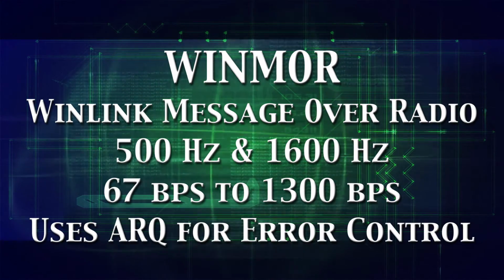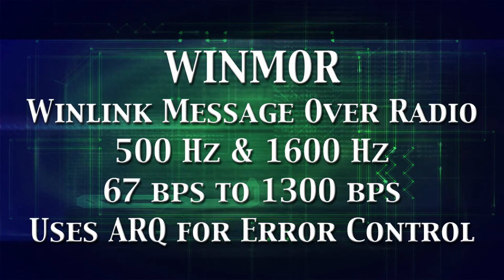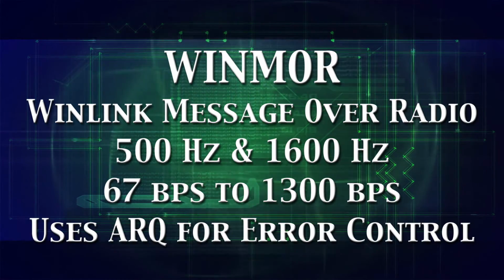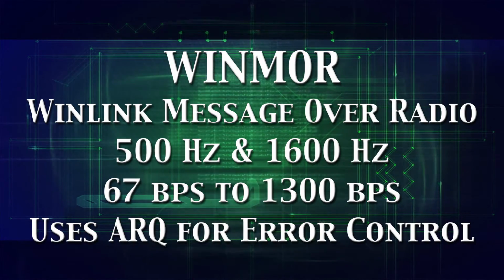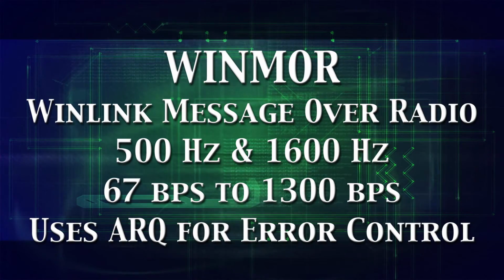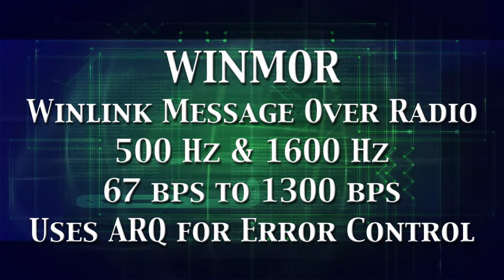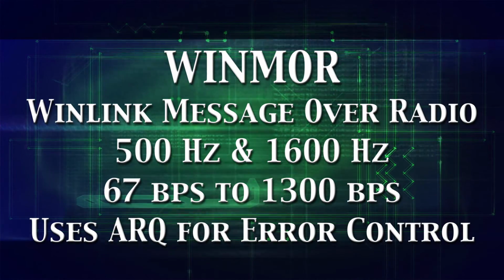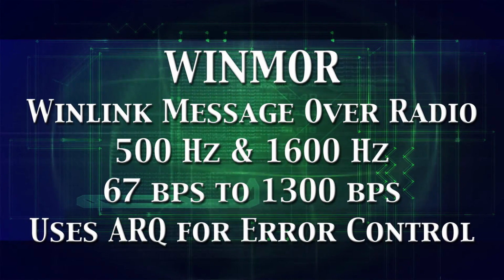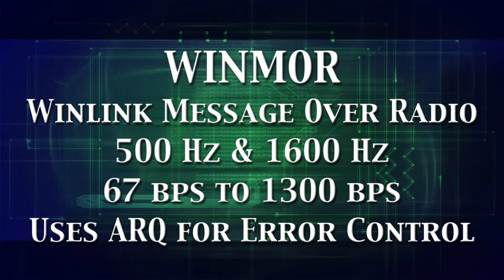When the sending and receiving stations connect using Winmor, they use an ARQ, or Automatic Repeat Request system, for error control. If the sender does not receive an acknowledgement from the receiver, it usually retransmits the data frame or packet. One can hear this send and acknowledge back and forth during a connection to the Winlink system.